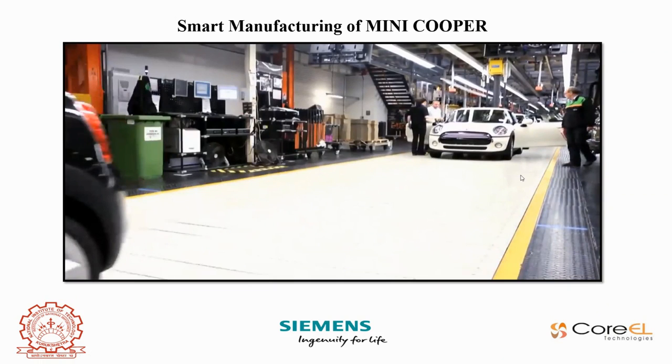That's it, guys. What have you observed in this video? All these things will be done by digital manufacturing softwares. First, the layout creation can be done by complete plant simulation software, which you are going to learn from next week. Next, all these precise robot applications and special applications can be done by robotic simulation software. How exactly the automobile or the component moves from one station to another, what the behavior of the station is, what inputs need to be adapted, how the human comes and does the operation, those applications can be done by process simulation software.